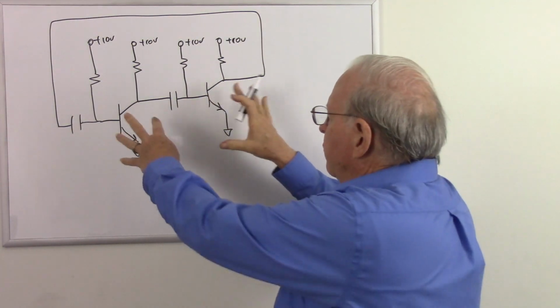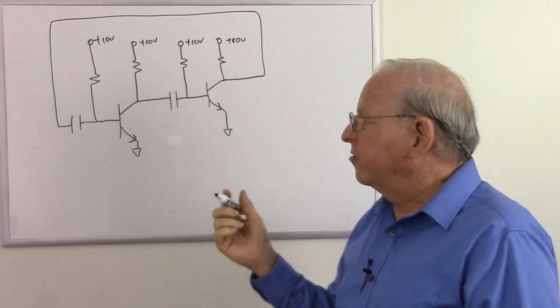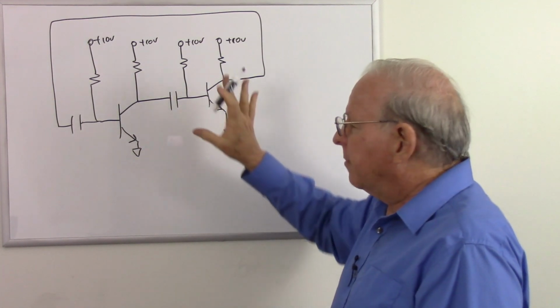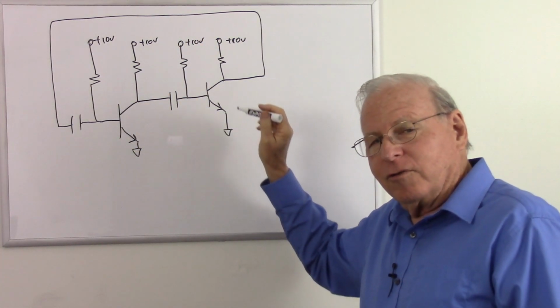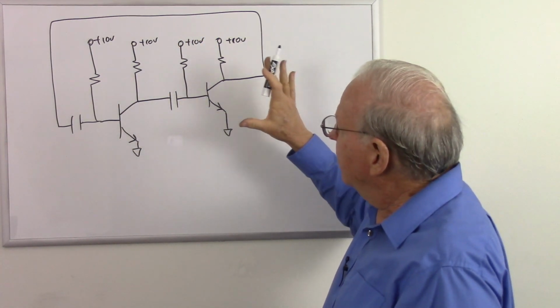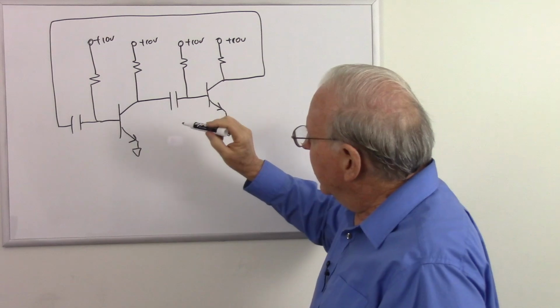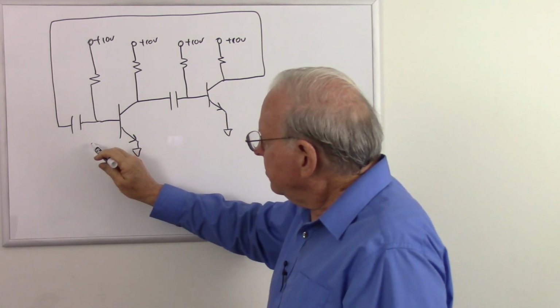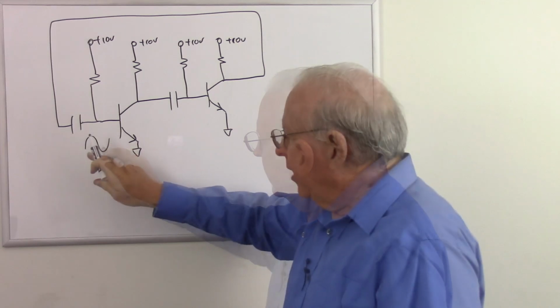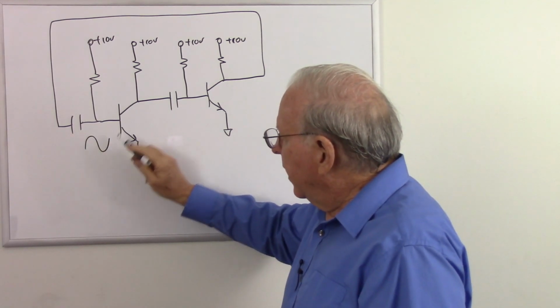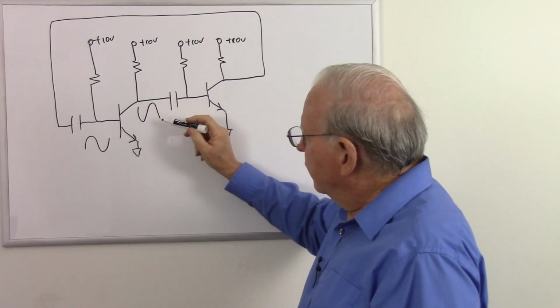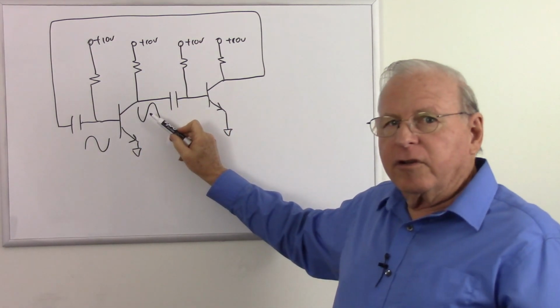Now we're looking at this as two amplifiers instead of the cross-connected transistors, but it's exactly the same circuit and will work exactly the same way, but I'm not going to explain it that way because I redrew it to explain it a different way, which we already did sort of, but I'll just reiterate it. So what we have now is a circuit where if we have a sine wave here, it goes up and down and back up. We're going to have a 180-degree inversion here. And so what we need to do is invert that again.